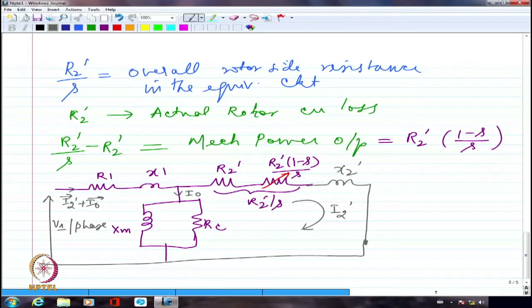And the rotor is carrying a current which is producing the torque, but that current is also coming from the stator. Where is it coming from? It is like a transformer. So if I look at it, the stator current will contain the magnetizing current as well as the torque producing component of rotor current. Both will be there.